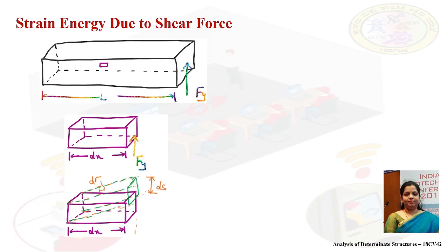Now let us move on to computing the strain energy due to shear force. In a similar manner, I have considered a beam of length L and a small element whose enlarged figure is as shown here. Now if I apply a force in the y direction and fix the area of the beam, the element will deform in this pattern. The deflected shape is as shown in the figure, and the deflected length is ds.